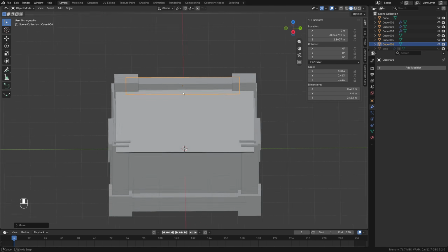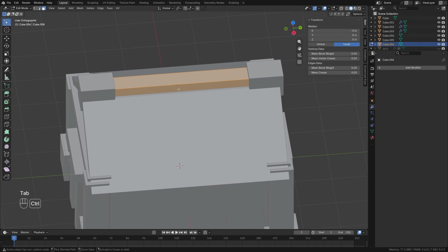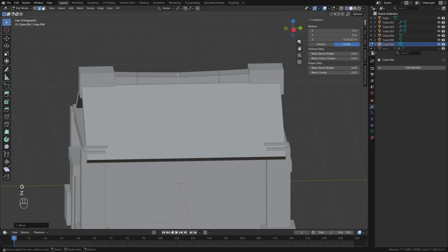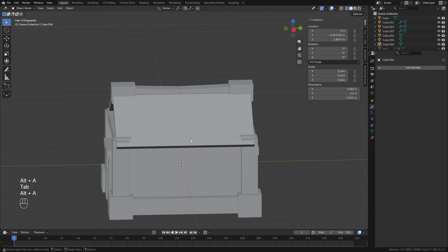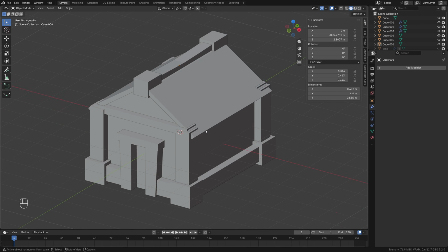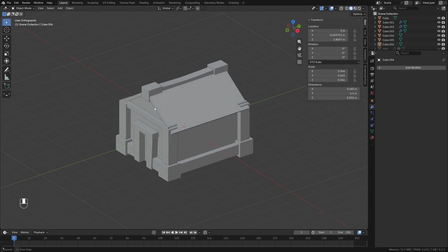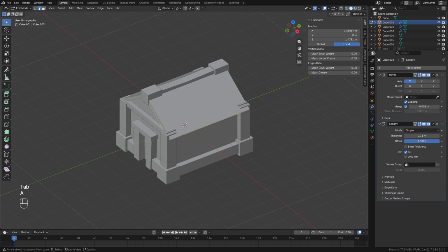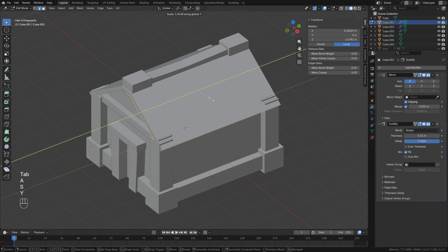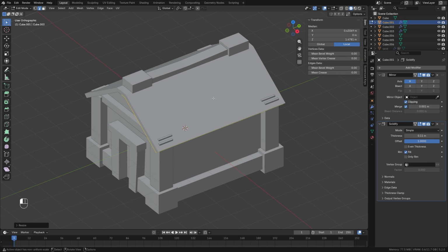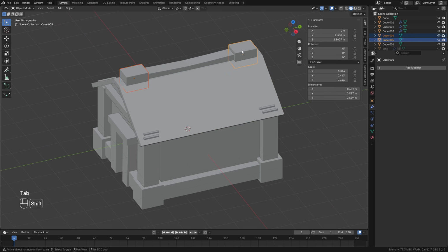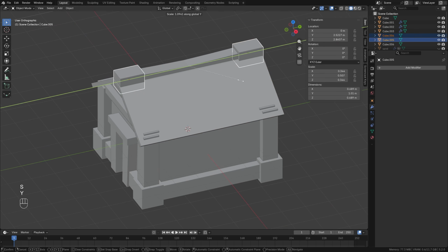You can leave this beam flat. You can rework it a little in Edit Mode using Ctrl plus R to add 3 cuts. G plus Z lower it a little, and then select the central one and also G plus Z lower it a little. Such small elements across all parts of your house will add variation. Because plain rectangular cubes don't look quite good, but you will have to spend significantly more time on them. Well, and now let's rework the roof a little. And now, when we see everything, S plus Y, we make it even a tiny bit bigger, roughly of the following dimensions. Well, and accordingly, possibly, these cubes we will separate along Y.